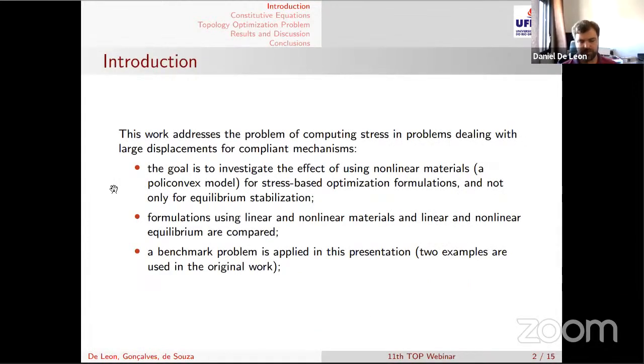The main goal of this research is to study the influence of the nonlinear material in stress-based problems in compliant mechanisms of large displacement. There are a couple of works dealing with nonlinear materials for geometrically nonlinear problems, but looking for the stabilization of the problem, most of all using Newton-Raphson schemes. Newton-Raphson schemes sometimes lose the path of convergence in topology optimization of large displacements. But there are just a few works dealing with nonlinear materials in stress-based problems, and we think this investigation for compliant mechanisms was done for the first time.